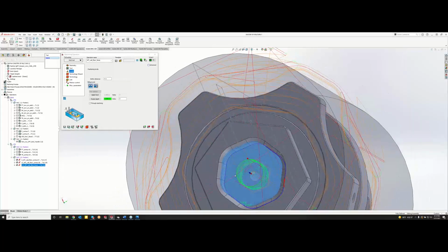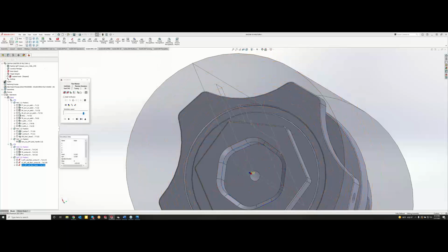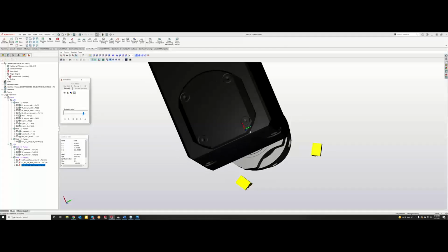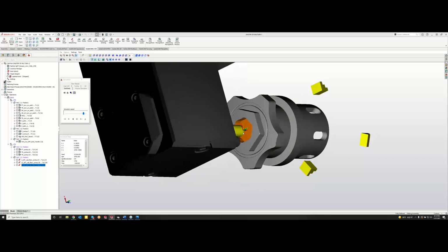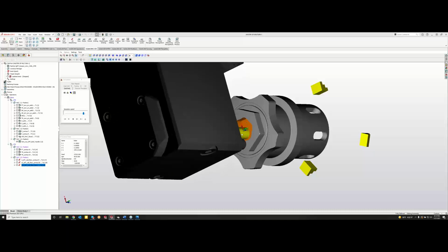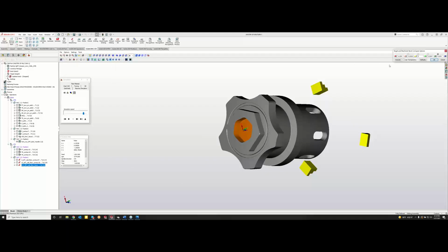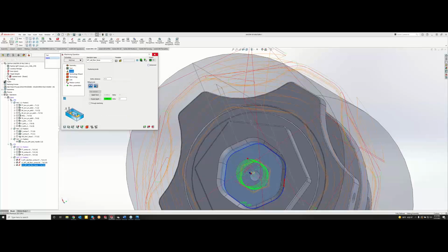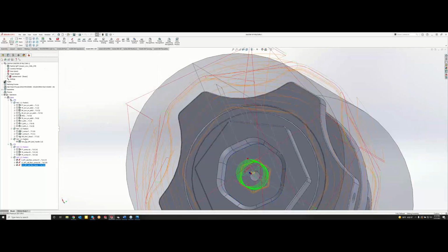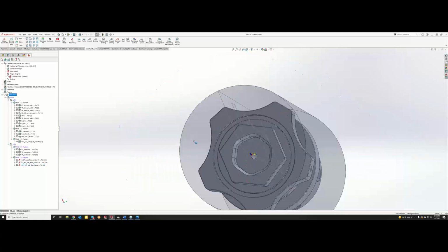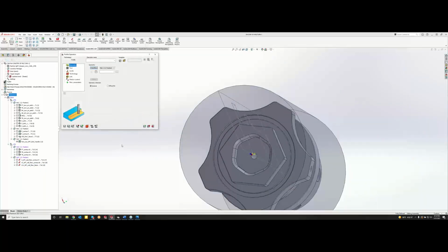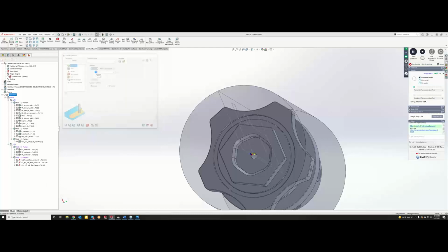And I can see that I got all my material out of there. Just do a quick solid verify here. All right. Make sure we're up to size. Yep, we're good. So now we can start focusing on those chamfers. What I'm going to do now is turn off all my toolpath, and we're going to do our chamfers with a profile operation. So we're on Mac 2, position 2, which is the same as what we wanted to be on.